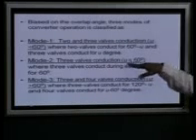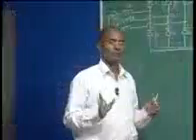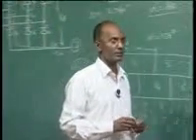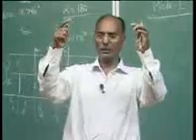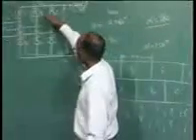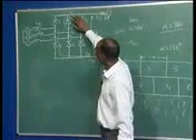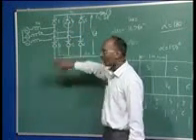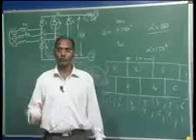Once it is 60 degrees, at all times 3 valves are conducting, 2 from one limb and 1 from the other, maybe 2 from lower and 1 from upper, or 2 from upper and 1 from lower. So all the time in mode 2 the 3 valves will be conducting. Now once U is more than 60 degrees, the conduction becomes 3 valves and 4 valves.